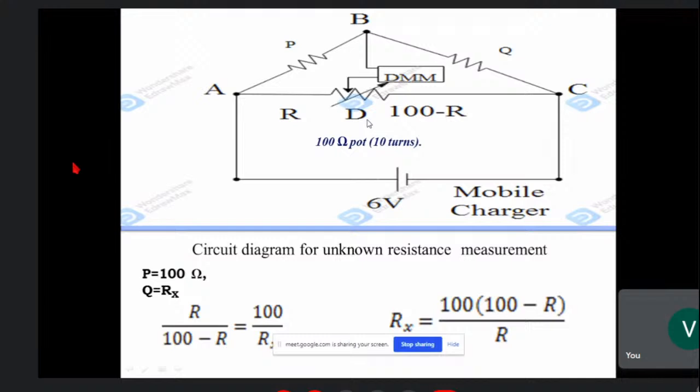Maybe there may be some error of 1 or 0.1, I don't know that. No, actually, sir, 5% tolerance is there. Okay, so 5%. Actually, in place of 100, it will give you 5 ohms more or less. 102 ohm, 102.3 ohm, I have found. Okay, so the answer to the question of Narayan, you can measure the resistance of both